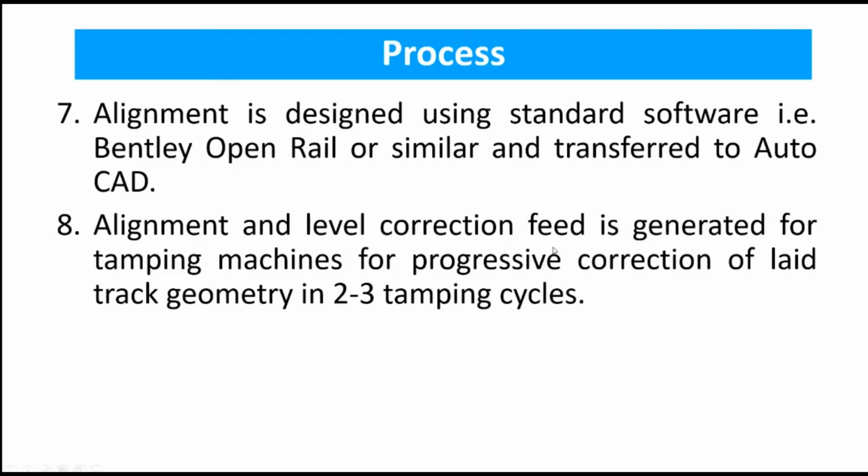Then alignment and level corrections are fed into the ALC of the tamping machine, and with progressive rounds of tamping, the existing profile is corrected and brought as accurately as possible to the designed alignment, which has been designed in step 7.